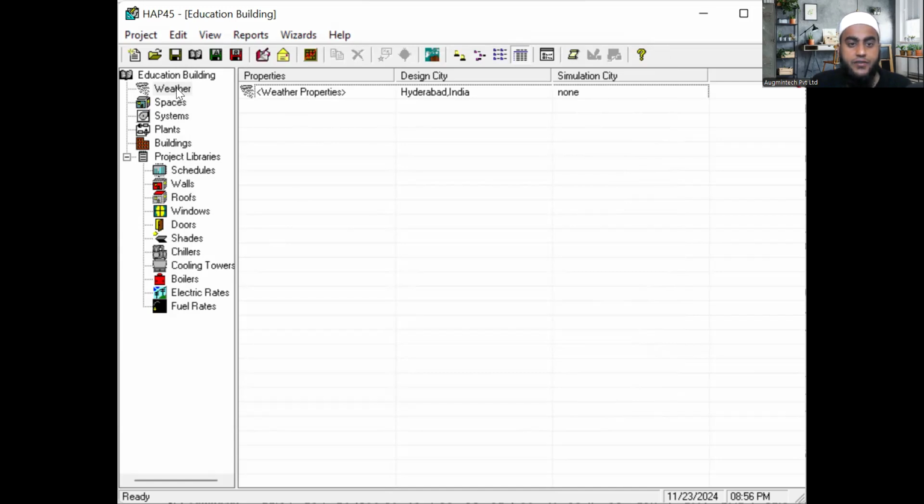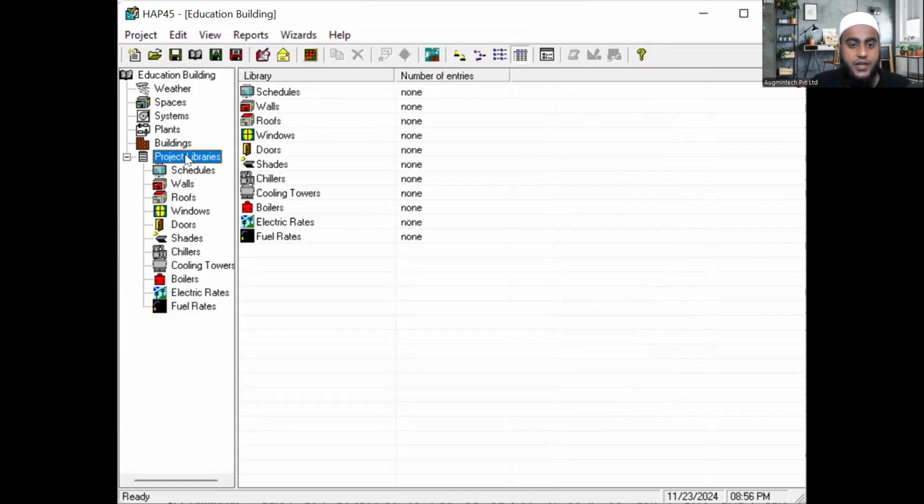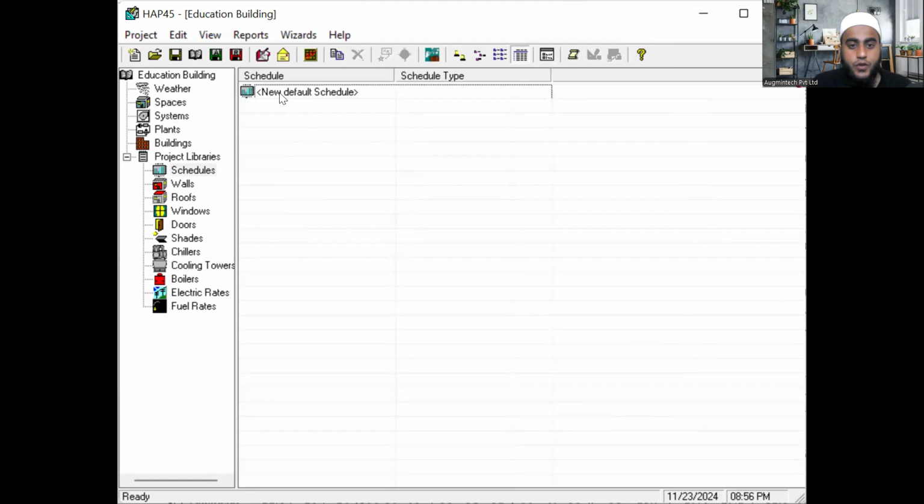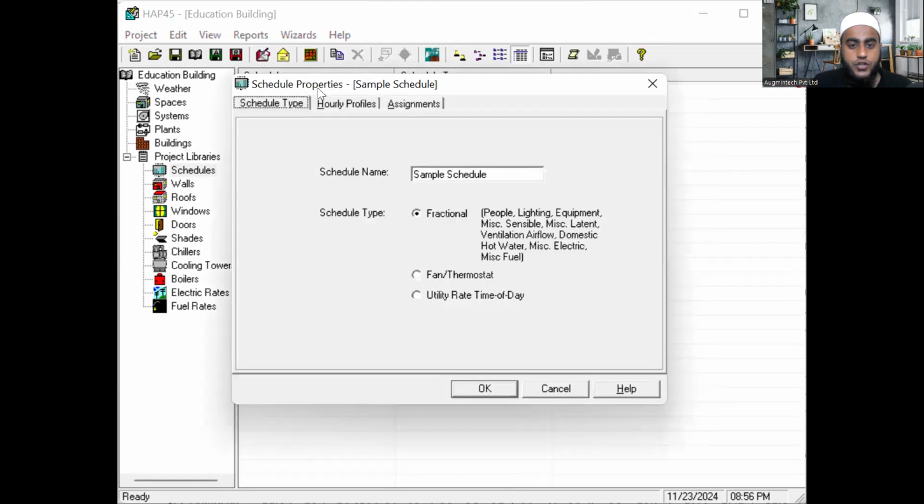Now, after entering this, what is next? Project libraries. Next, hit on project libraries. And here we first have to prepare the schedule for lighting, electrical, people. So how to prepare the schedule? Select the project library, double hit on schedule. Now you will get one option, new default schedule. Double hit on new default schedule and let's see the schedule type.